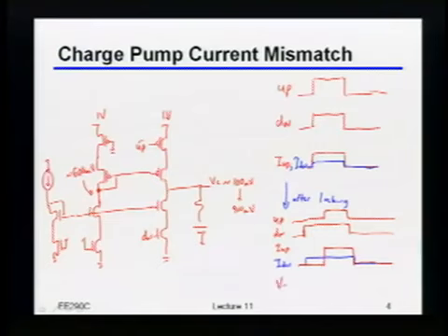And I'll give you maybe a hint. What happens to the control voltage every time we do this? You get a reference spur? Yeah, you get a reference spur, right?